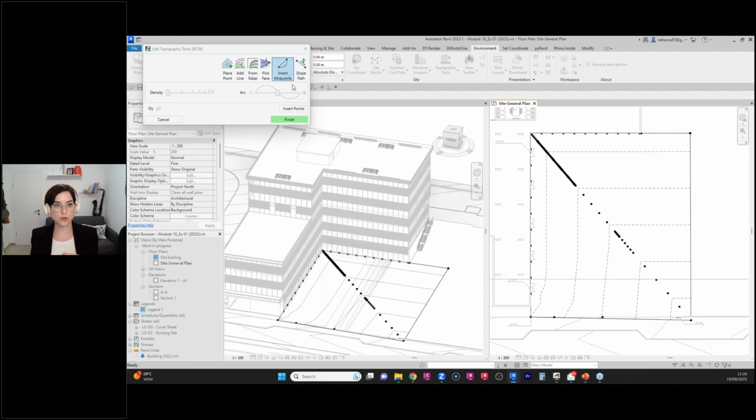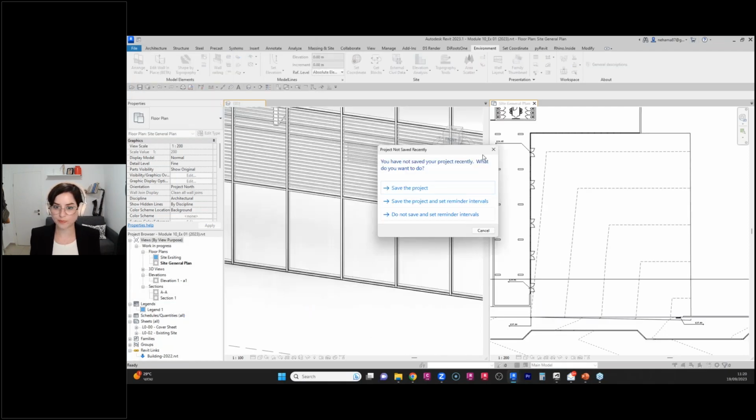Let's use the interpolation tool, the insert midpoint. And the insert midpoint is just like its name. I'm going to select 2 points. Let's go with 1 and 2. And Environment will optimize the placement of these points to kind of smooth my surface. Now let's do it again. 1, 2, insert points. And I get a very, very smooth surface. I'm going to click on finish now.